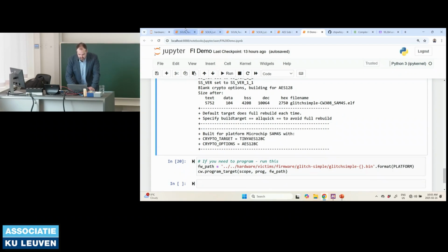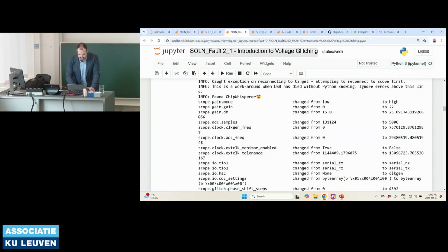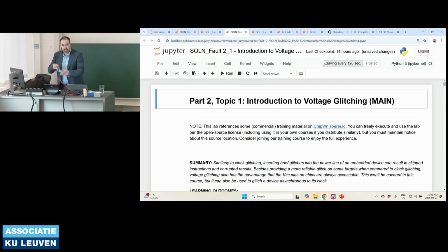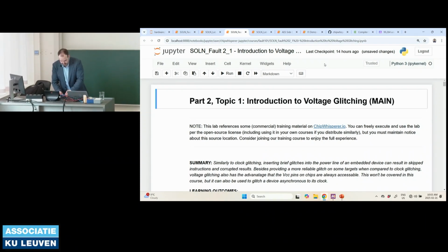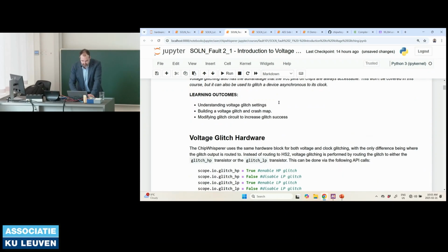What I'm going to switch to first is voltage glitching attacks. To do this, I'm going to use my ChipWhisperer, which has that little crowbar set up, and connect a line to the crowbar. It'll take the power rail down on the device at a really specific instance in time.